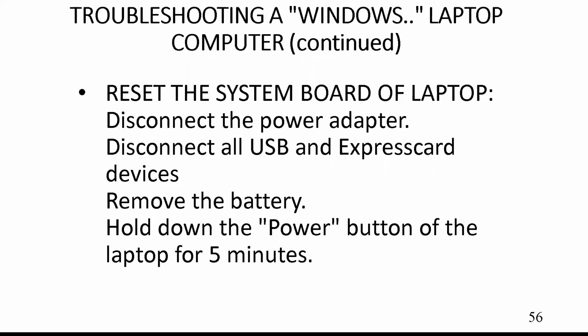Okay, let me go over the procedure real quick, and you can read more about it in some of the websites that I will then refer to. Disconnect the power adapter from the laptop and from the power outlet on the wall. Disconnect all USB and express card devices. You don't want anything attached to a laptop that might possibly feed even some residual voltage or current into it. Remove the battery of the laptop. Hold down the power button. That's that push button that you normally just push down for a second, for 5 minutes.